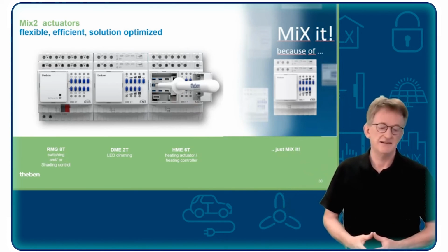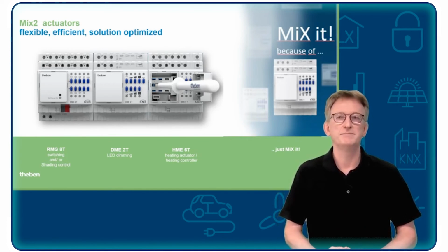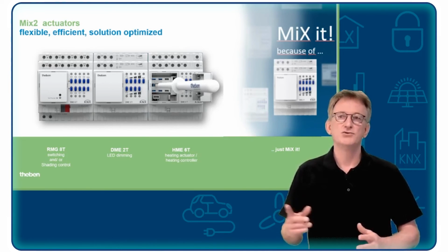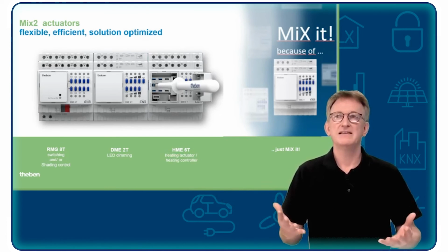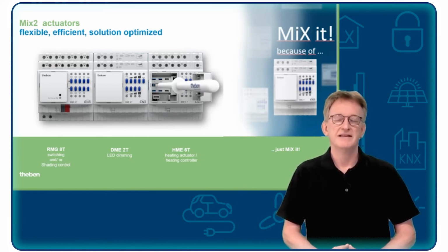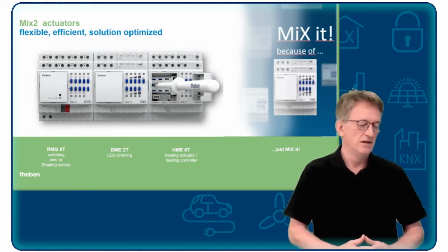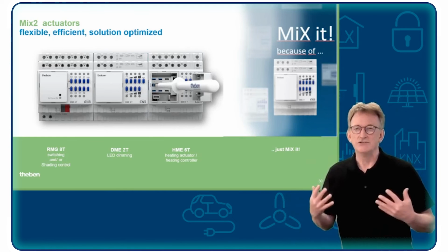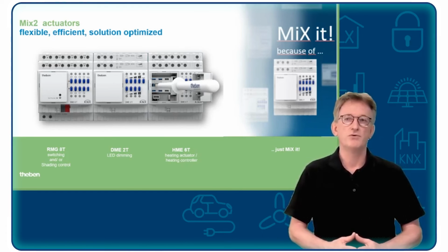And even in ETS, it's much easier to configure and program these devices, because you do not have to assign central commands to each device, just to the base module, and that's it. And the nice thing is that you now have many devices available for DIN rail supporting KNX Data Secure. And this will get more and more important.